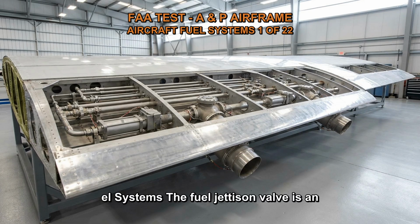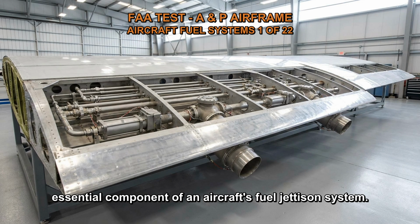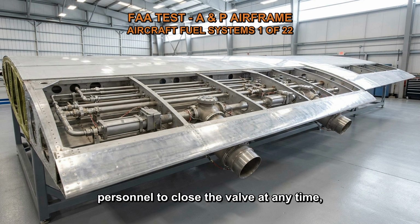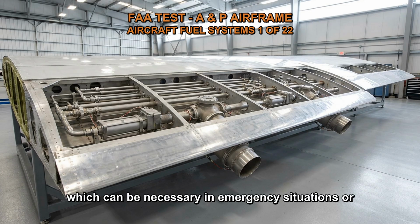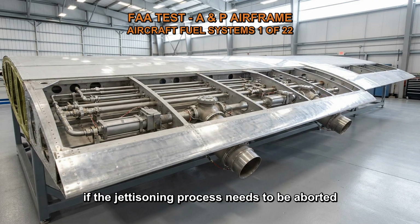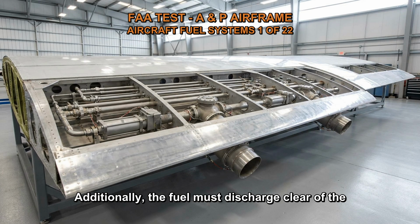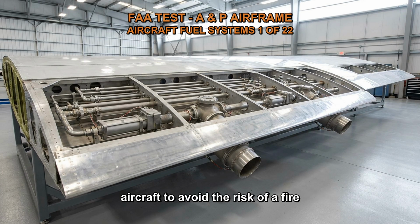The fuel jettison valve is an essential component of an aircraft's fuel jettison system. This valve must be designed to allow flight personnel to close the valve at any time, which can be necessary in emergency situations or if the jettisoning process needs to be aborted for any reason. Additionally, the fuel must discharge clear of the aircraft to avoid the risk of a fire or explosion. Therefore, option A is the correct answer.